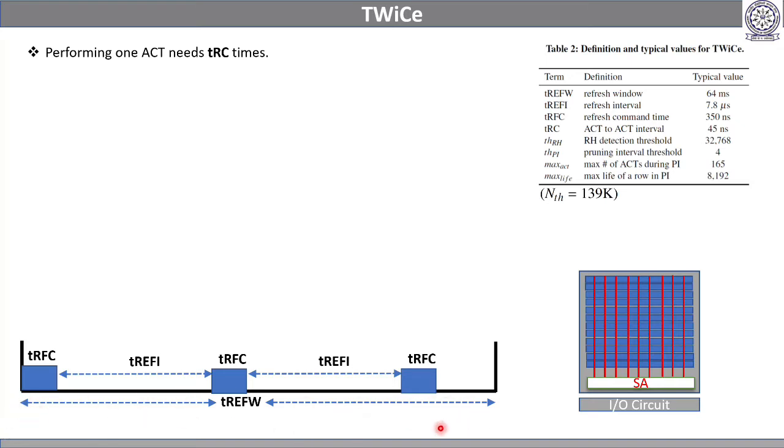During this refresh period, each row must be refreshed once. That is called periodic refresh, and you know how auto refresh is performed, what tRFC is, and how it is divided into multiple parts. So these two terms are very clear to you: tREFI, the refresh interval, and tRFC. This is called tRFC. This is tREFI. I've explained it many times. tRC means row cycle time, the time from one ACT to another ACT, meaning one activation to another activation. This time is called tRC.